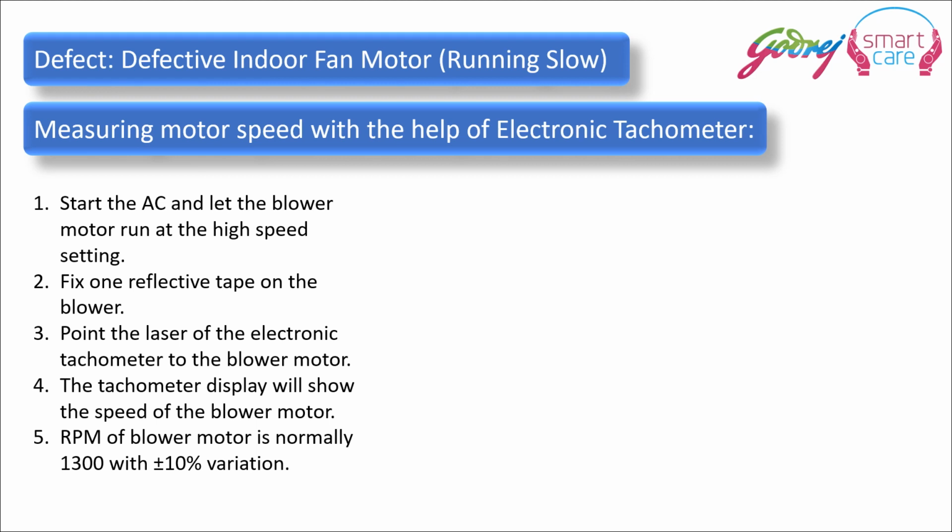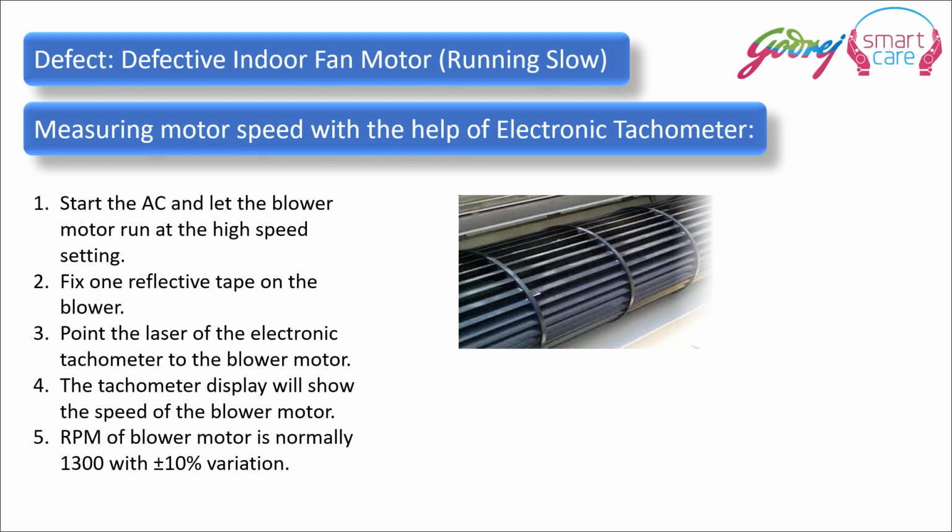Fix one reflective tape on the blower and point the laser of the electronic tachometer at the blower motor. The tachometer display will show the speed of the blower motor. The RPM of the blower motor is normally 1300, with plus or minus 10% variation.